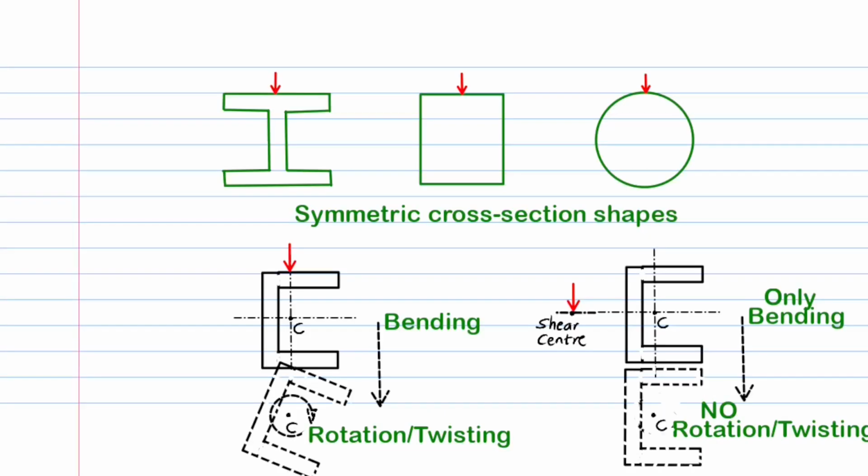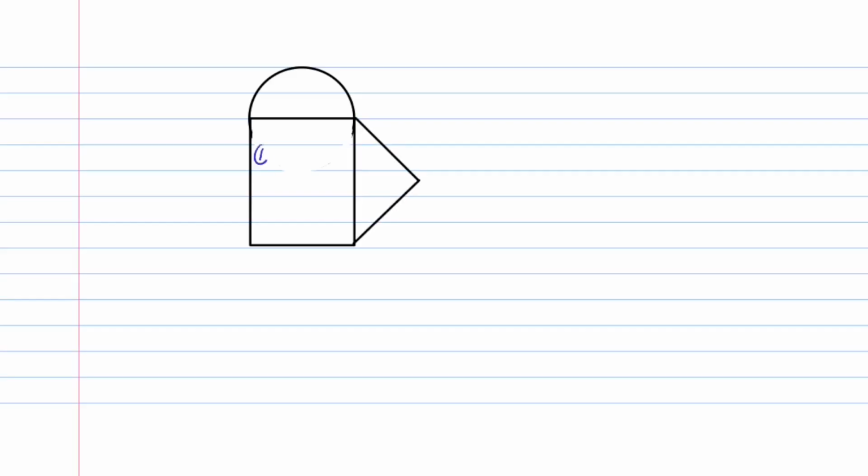The shear center is the point where a load can be applied such that the beam only bends with no twisting. We shall deal with only symmetric beams, the symmetry being with respect to the vertical plane passing through the centroid, for calculating the bending and shear stresses in later chapters. As such, for this chapter dealing with the calculation of area moment of inertia alone, we shall consider both symmetric and unsymmetric sections though. Without any proof, let us understand how to calculate the centroid of a complex cross-section shape consisting of n basic shapes.